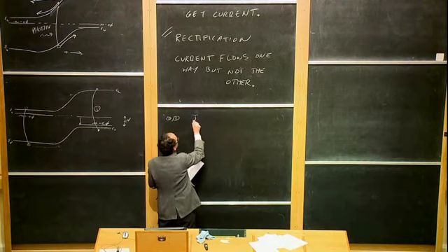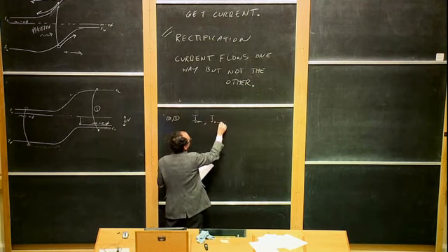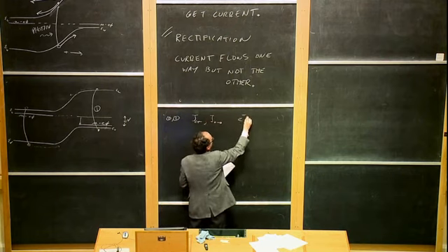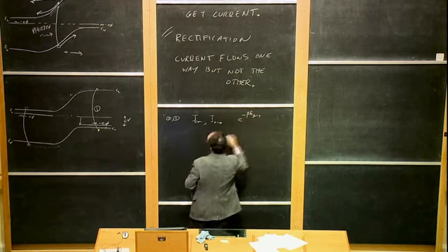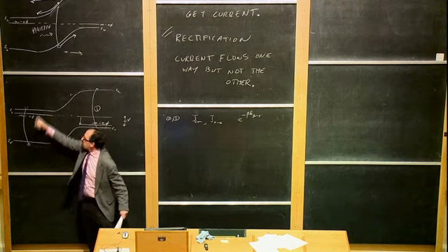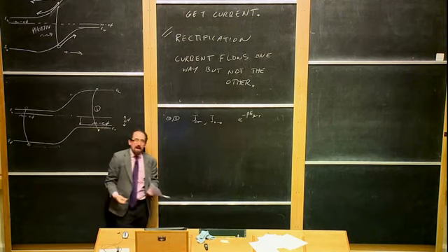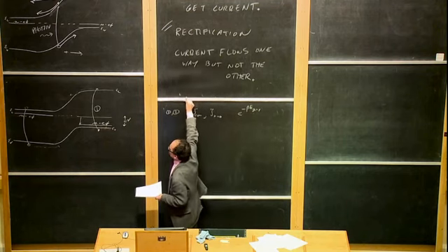that's either an electron going to the left or a hole going to the right, and either way, its rate is e to the minus beta E gap, because the limiting step is to get the electron up into the conduction band or get the hole down into the valence band, and that costs you the gap energy, so it's activated. Okay? So that's one thing that can happen that can cause current.